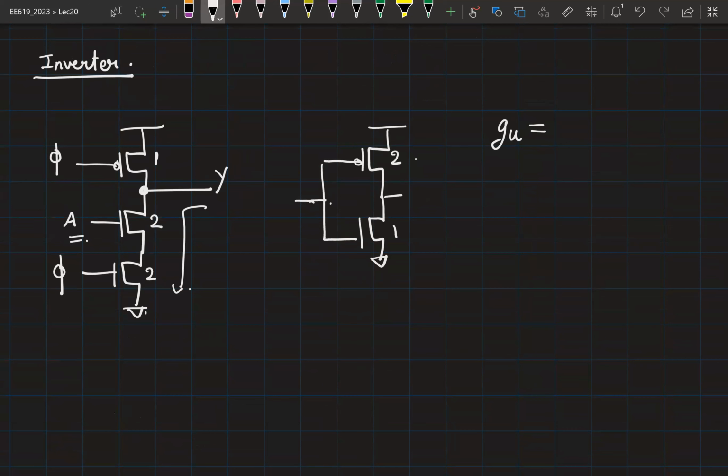The ratio 2:1 we keep in a reference CMOS inverter so that the pull up and pull down network has the same RC, right? In this particular case, the pull up network has half a clock period to charge. So our priority now is to focus on the pull down network. Is that clear?